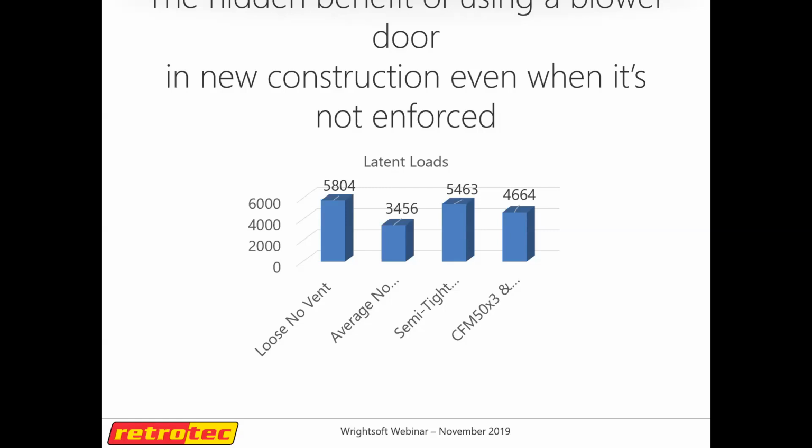We can't design for that, because you might end up having built a tighter house and you might end up needing more outside air. So ASHRAE 62 is built to provide sort of the maximum reasonable amount of outside air for that situation. But if I actually perform a blower door test, or someone else, the HERS rater, does it, and I'm the HVAC professional and we share our information, and I have those numbers, if I can plug in a CFM50 number or any other blower door test data, right?